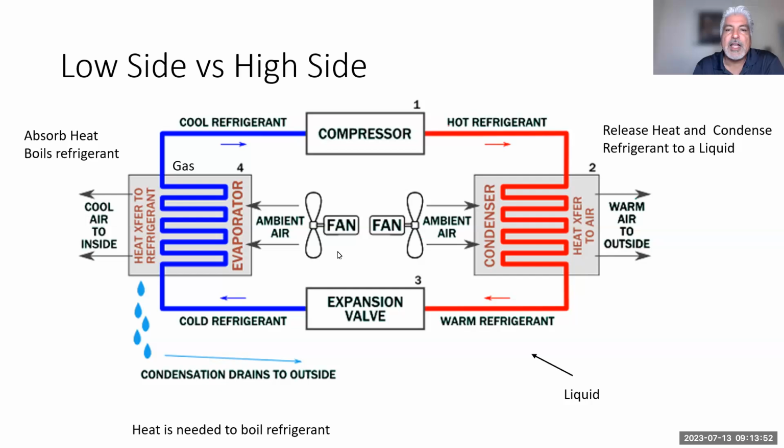As we look at this diagram, we'll see the compressor outlet, where the refrigerant is red in color. What it's supposed to do is condense, and to condense means to go from a vapor to a liquid. In order to do that, we have to get rid of heat. In turn, that refrigerant will be in a liquid state going toward the expansion valve, where its flow is regulated. Then we go into the evaporator, where warm air is going across the evaporator, and we're carrying and absorbing that heat. At that point, we're taking it back toward the compressor, and the circulation repeats.